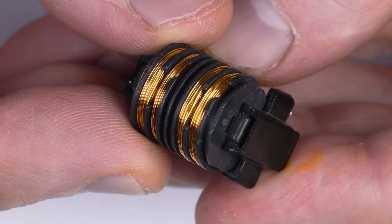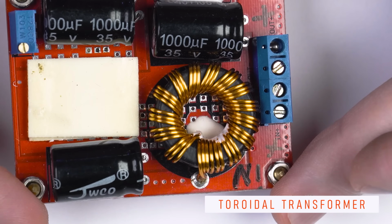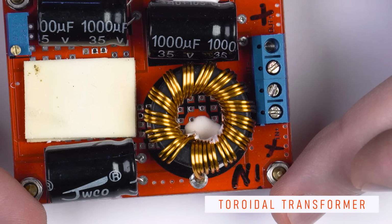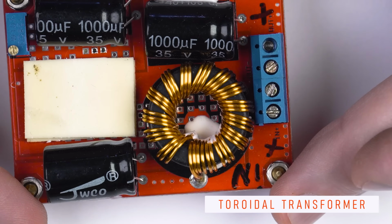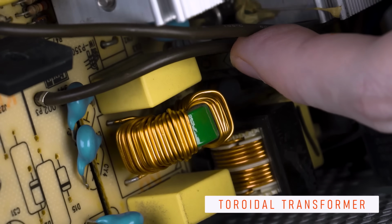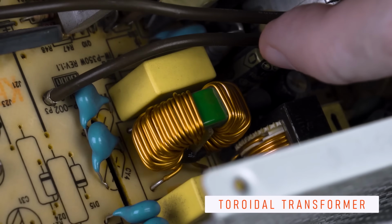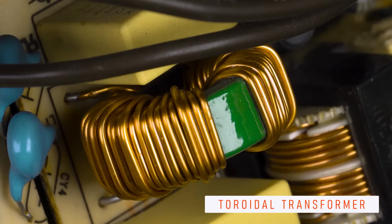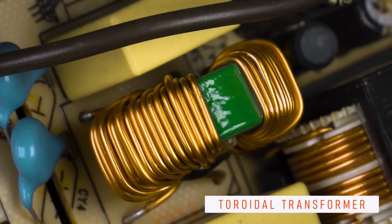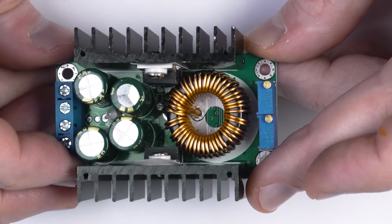There's another, also very common layout, in which the core is made up of a solid ferrite ring. It's called a magnetic circuit, and the windings are laid around its circumference perpendicular to the tangent. Such devices are called toroidal transformers. The advantages of such a design are smaller weight and dimensions, a reduced noise level, and most importantly, a higher efficiency. The obvious disadvantage of a toroid transformer is the more complex process of winding, which requires a special device. At the factory, however, toroid winding is performed by a robot, which significantly reduces production costs.